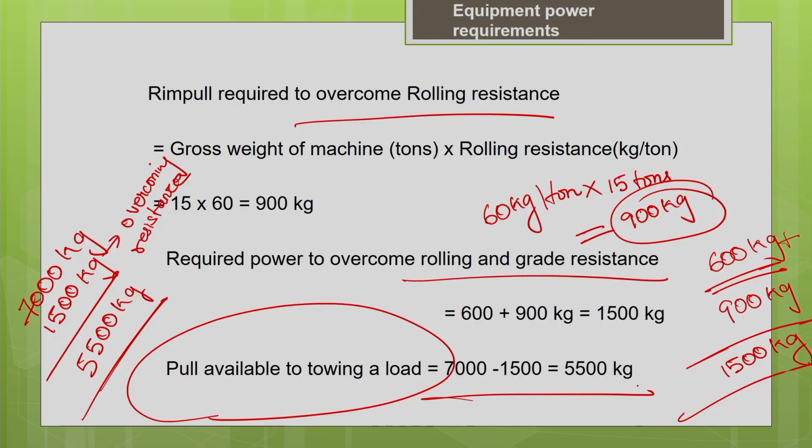So we were discussing the usable power estimation. We found that the usable power depends upon the project conditions, like the underfoot conditions prevailing in the project site. Out of the total power available for the machine, some portion is used for overcoming all the resisting forces in the project site and to make the machine move. After overcoming the resisting forces, only the remaining power is available for towing the load or doing the actual job. Okay. So that is the usable power.